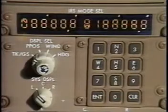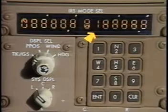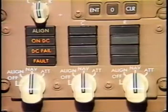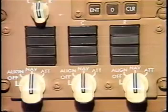During the same period, the IRMP's data display indicates a north-south all-eights display for latitude and an east-west 188 degrees and 88.8 minutes for longitude. During the next 8 seconds, all left IRS mode and status annunciators return to normal.